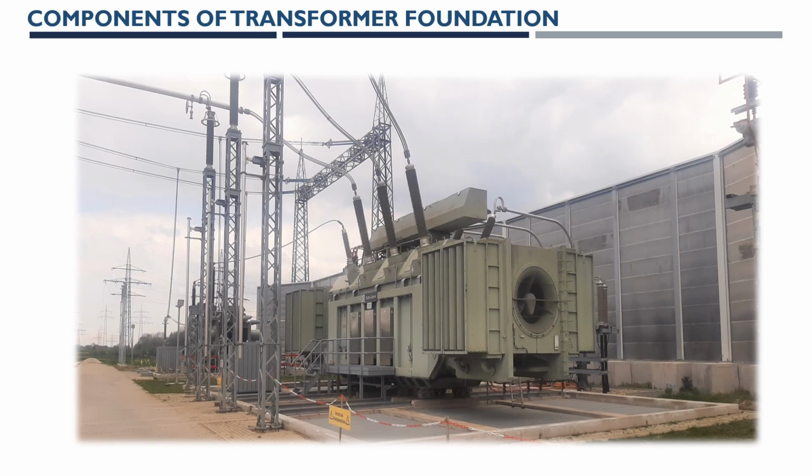So this is a picture we have seen in our title sheet. In the title card we can see this picture which is having a sound barrier wall behind the transformer, which is a separated foundation, and these are the transformer bund walls which run peripheral to the transformer. So the platform support having the rail and hauling walls, transverse walls here, gratings, and some cable support also running behind the transformer, which is all together in the foundation.